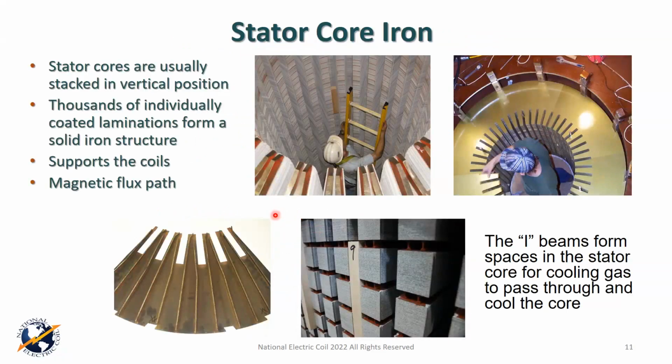All right, the stator core itself, as I mentioned to you, the stator cores are made up of thousands of laminations in most of the machines. The gentleman over here, he looks like a Las Vegas dealer dealing blackjack, but he's dealing laminations to put them in place on these key bars. This is, I believe, the same machine we saw a couple of slides ago. The only difference is he's sitting on a platform, and as you can see, he's coming to the end of the stacking, and he's putting in these laminations.